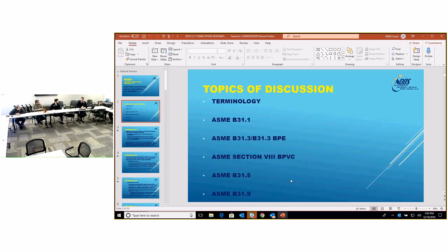That's interesting. A lot of owners will actually try to work with Alliance or United XL or FM Global, whatever their insurance company is, and that allows them to keep their rates down. But there's a negotiation that happens there, and that can cause delay in construction and execution of the drawings, because the insurance guy may want to see a particular system follow B31.3 instead of B31.9, even though it was bid with B31.9. That may just be a blanket, this is what we want to see.